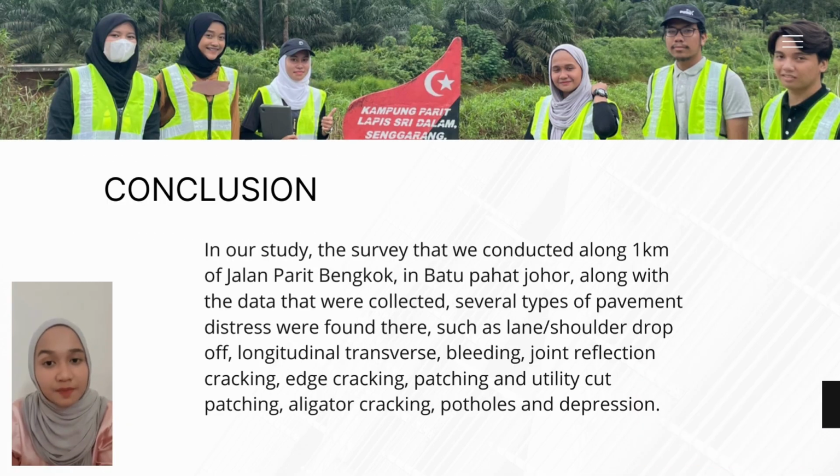So, this is the last part of our project, which is the conclusion. In our study, the survey that we conducted along 1 kilometer of Jalan Parit Bengkok in Batu Pahat, Johor, along with the data that we collected, several types of pavement distress were found there, such as lane shoulder drop-off, longitudinal transverse cracking, bleeding, joint reflection cracking, edge cracking, patching and utility cut patching, alligator cracking, pothole and depression.